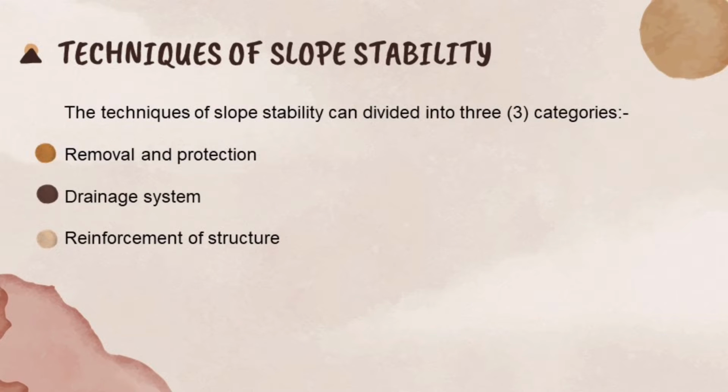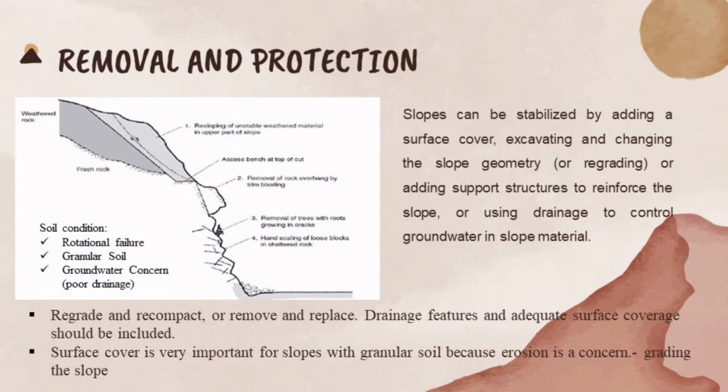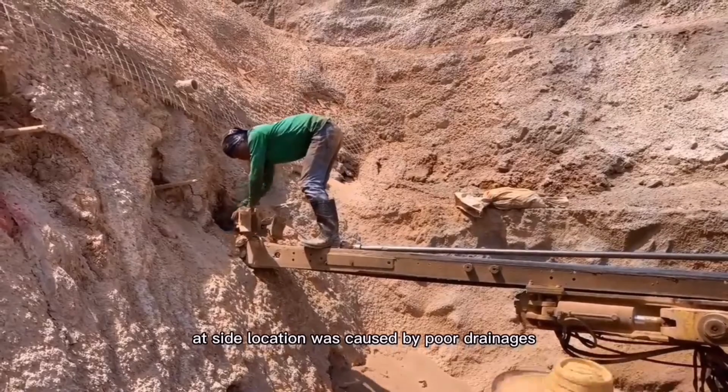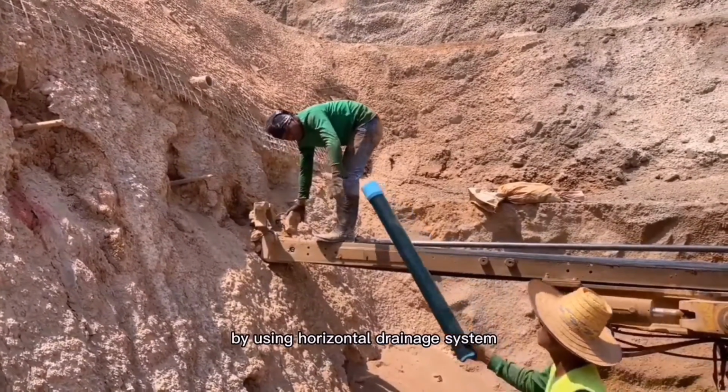Techniques of slope stability can be divided into three categories. Slope can be stabilized by adding a surface cover, excavating and changing the slope geometry, or adding support structure to reinforce the slope. Slope failure at the site location was caused by poor drainage, so we will improve the drainage system by using a horizontal drainage system.